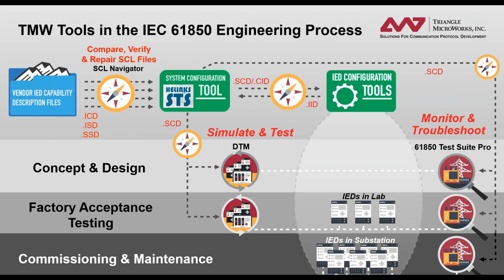For the type, normally the relay should be able to subscribe to any type if there is a compatible logical node later on to use it. If this is not the case, then there is the option to use, as Christoph has mentioned, the later binding and not allow additional xrefs. With this, the receiver can define exactly which data and which data type he is receiving.